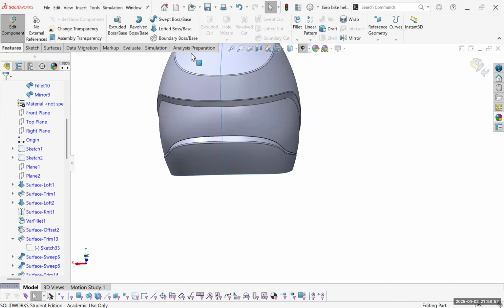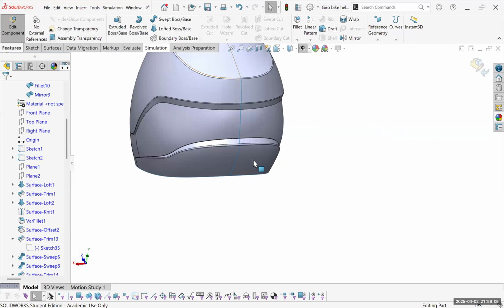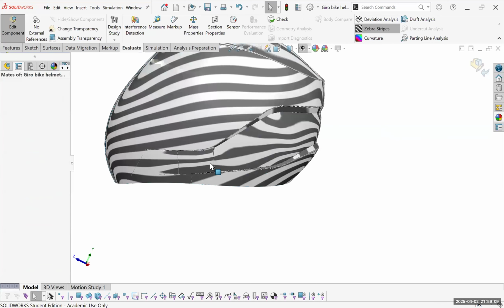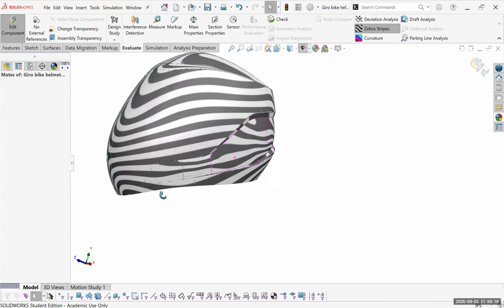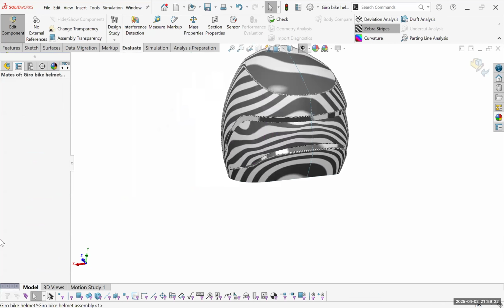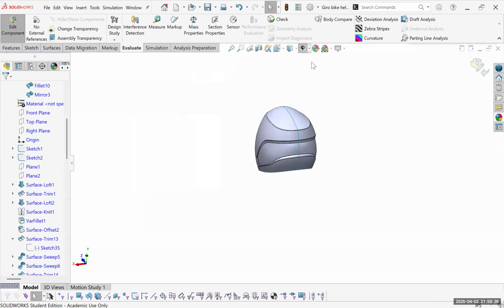So this is the goal, I'm trying to see if it's smooth, and if it's smooth, we'll delete that. Okay, that looks good. This got much better. Still, we have some funny stuff. I actually think my 3D sketch is too curved. This is pushing the surface. All right, I'll come out. We don't need the mirror, so make sure you get rid of it so it doesn't bother you.